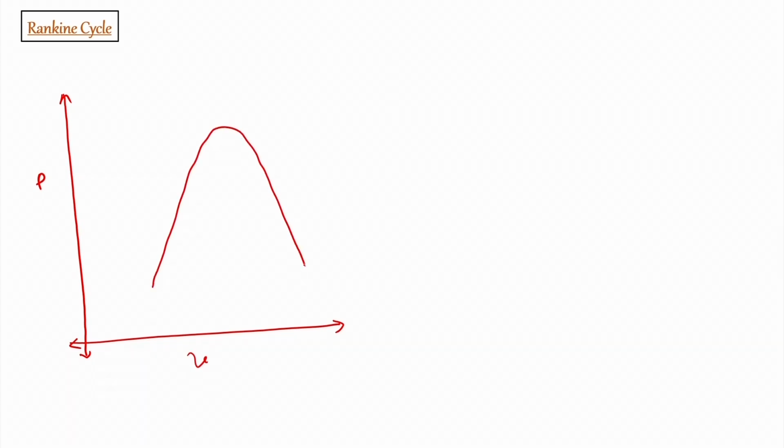Then we have Rankine cycle, and in this Rankine cycle, we know the working medium is water, and this water is used in two phase. So this cycle uses two phase material while doing the work. So the PV diagram for this cycle basically needs first to draw the phase change dome. Then 1 to 2 is basically isentropic compression, but since we are dealing with liquid, we will not see much compression, but there will be much pressure rise.